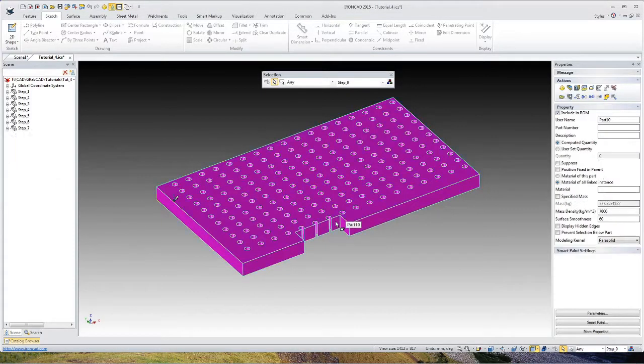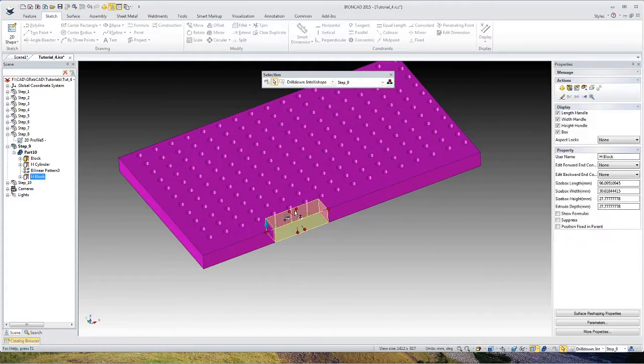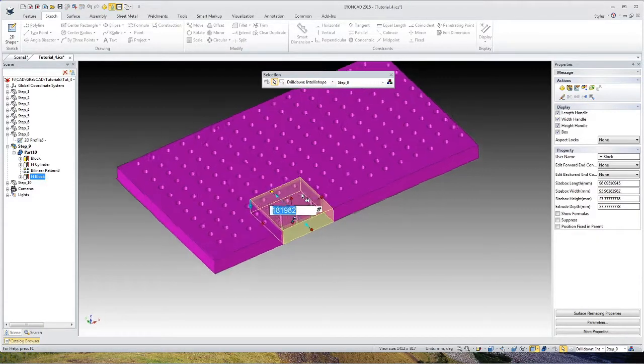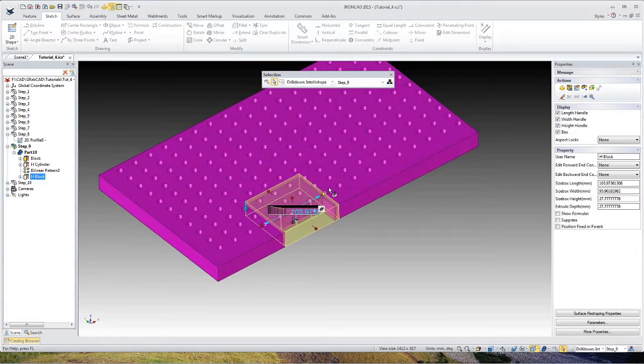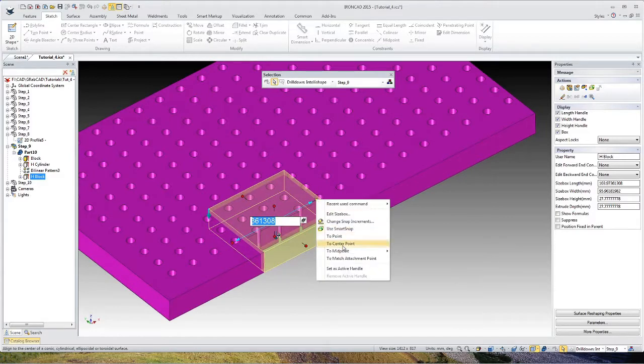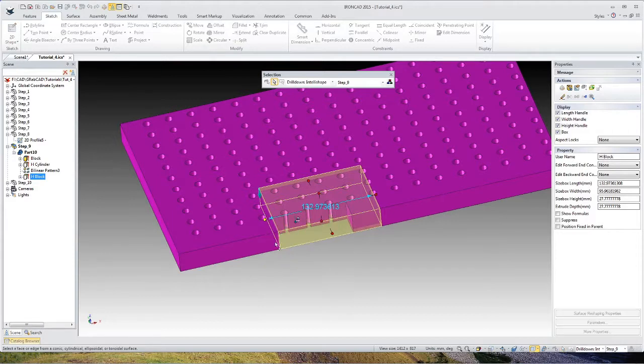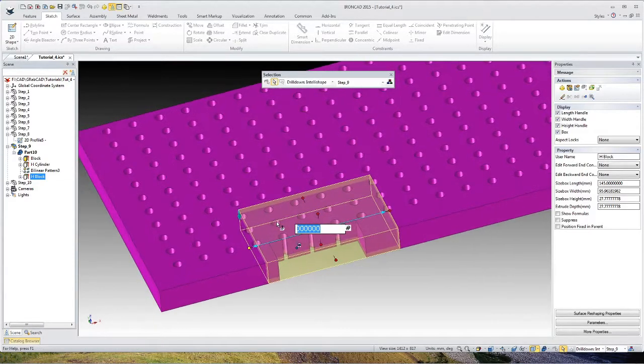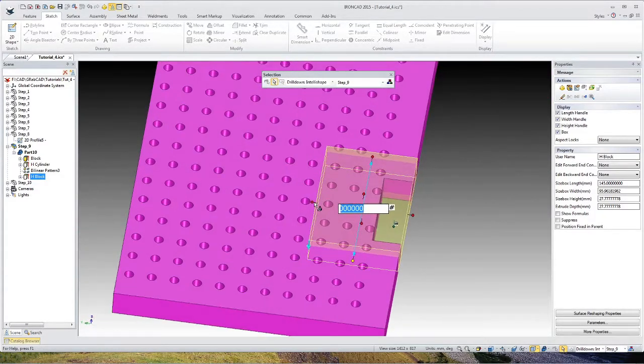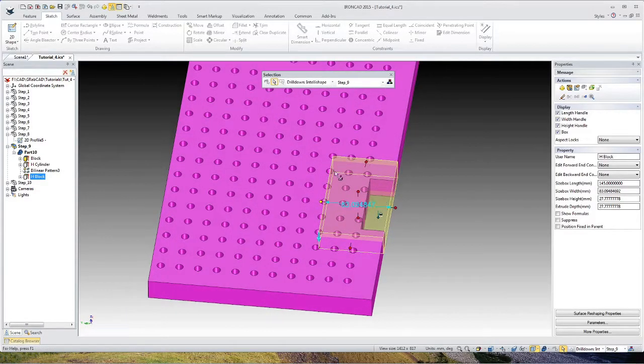And what that means is we can position our whole block here. So let's right click on that bubble here and go to the center point. Do that here, so we can reposition this whole block, and it's not actually changing the part, you see, so we don't have to wait for it to regenerate. So I'm kind of happy with that now.